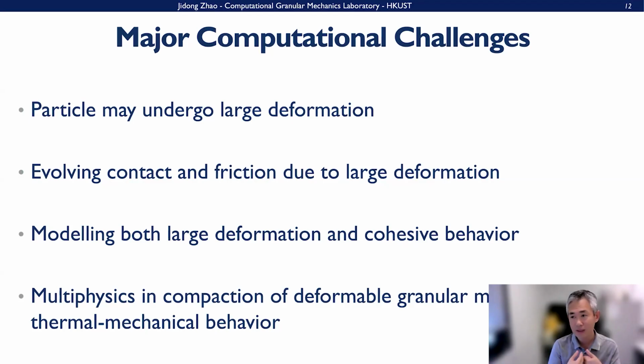With this contact area changing, there is the frictional behavior, and of course cohesion as well, because the powder grains are small and their physical and chemical properties make them develop certain adsorption forces and attract each other, developing cohesion.